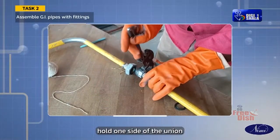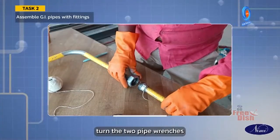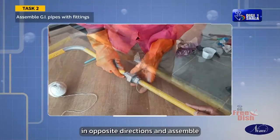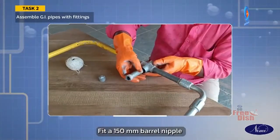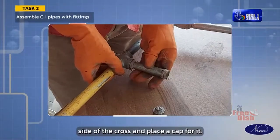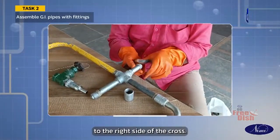Hold one side of the union in one pipe wrench and the ring of the union in the other. Turn the two pipe wrenches gently in opposite directions and assemble. Use grease or Vaseline on the union joint for easy disconnection. Fit a 150 mm barrel nipple to the left side of the cross and place a cap for it. Join another 150 mm barrel nipple to the right side of the cross.